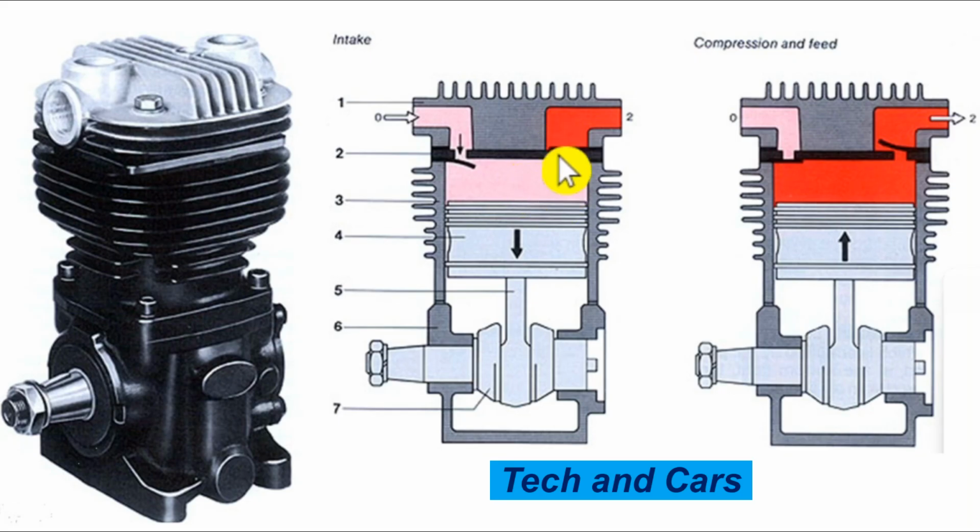Anything that can cause a leak if the external circuit is also leaking. So the compressor can't build pressure if there is leakage somewhere, if air is escaping elsewhere. So you have to check the entire system with a soapy water solution in order to pinpoint if there are any leakages. And the other thing that can cause the pressure not to build rapidly is if the piston ring is worn, or if the compressor cylinder is worn out.